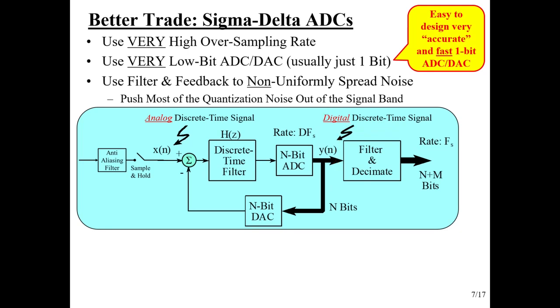But out here, this is before the A to D converter and after the DAC. So this is all done in analog. And I'll comment on it again in just a few slides, but it's done with a particular type of capacitor-based technology where the capacitors hold the samples. So there's no quantization, but there is discrete time. So that's the idea. And I'll give a name to that in just a little bit.